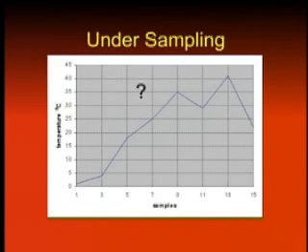If the number of samples collected is reduced by half, that is, samples are collected at every odd interval of time, the resulting reconstructed signal is very different from the original signal. The peak in the continuous signal at 34 degrees centigrade and the dip at 23 degrees centigrade are altogether missing from the reconstructed signal. This is due to the small number of samples taken. A better approximation of the original signal can be obtained by increasing the number of samples. An infinite number of samples very accurately represent the original continuous signal.